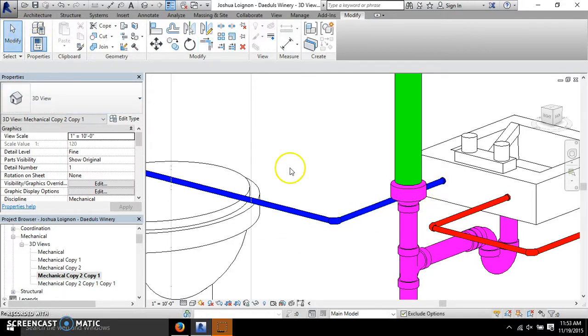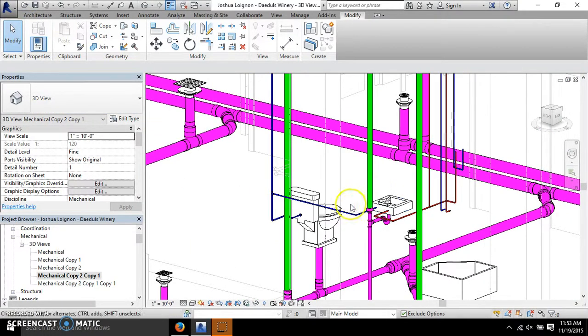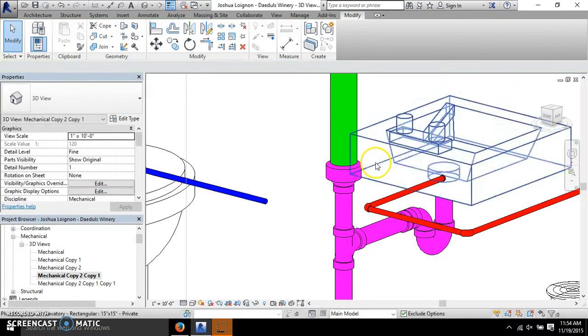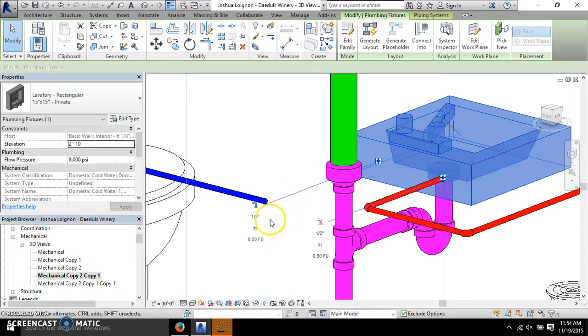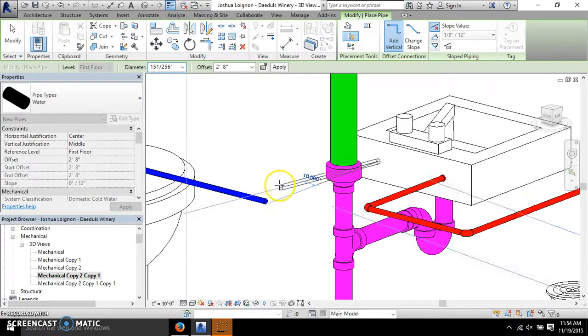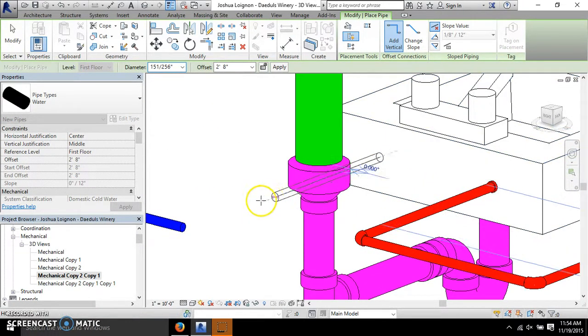Easiest way is you can just trim. You can trim that way, or if I'm drawing this pipe, if I deleted this out, and then once you hit create pipe here, you get the same functions as I was showing you for the pipe. So I can come out, this thing's at 2'8", but I could come out a little bit, say I got to go into the wall.